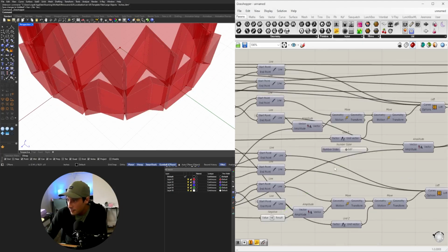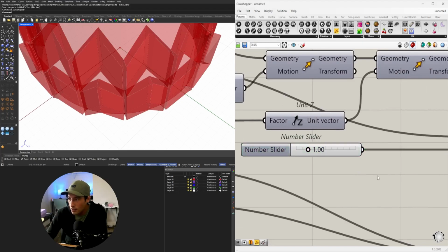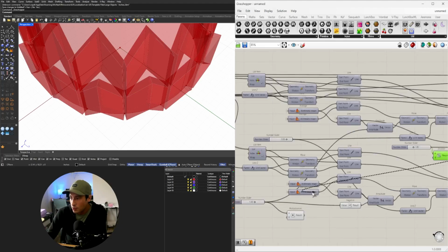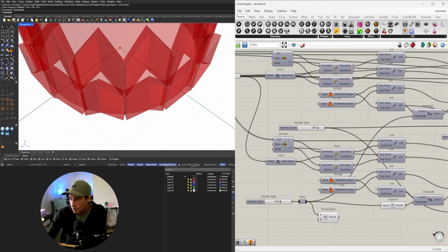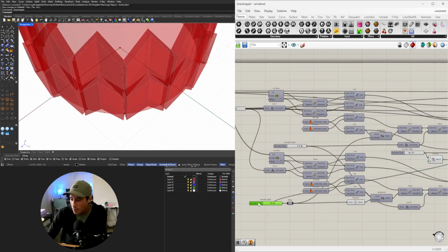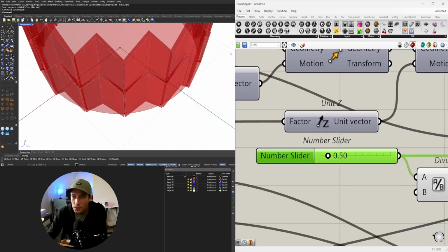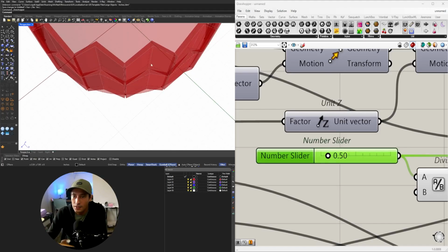If the important thing here is the tile size, if I want the tile size to be 1, well then we do 1 divided by 2, and that would be the value used for all the offsets. So it's the same thing, it just matters what functionality you want. Do you want your offset to be the important thing, like to be the extreme, or do you want it to be the tile? Like if you have a tile that's 1/2 inch, how much do you need to offset that by to create that gap there?